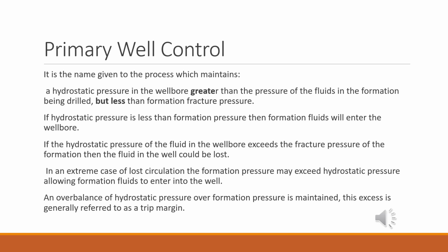In an extreme case of lost circulation, the formation pressure may exceed hydrostatic pressure, allowing formation fluids to enter into the well. An overbalance of hydrostatic pressure over formation pressure is maintained. This excess is generally referred to as a trip margin.